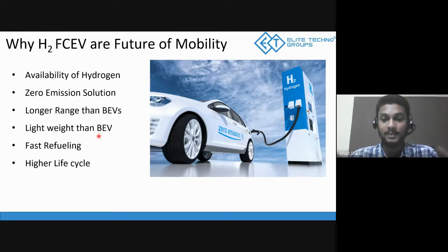In battery electric vehicles, around one third to half of the weight of the entire vehicle is because of the batteries. But fuel cell, as we saw in the Ragone plot, stores high energy within less weight. So it gives lightweightedness to the vehicle, which can be used to get a better range.